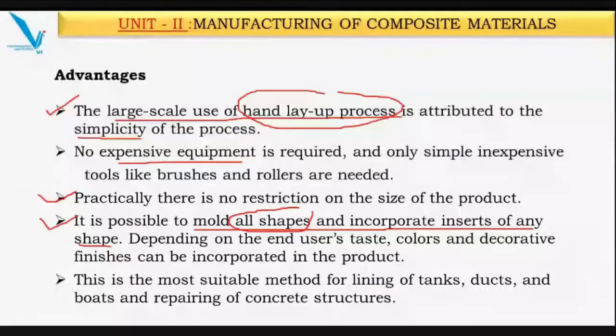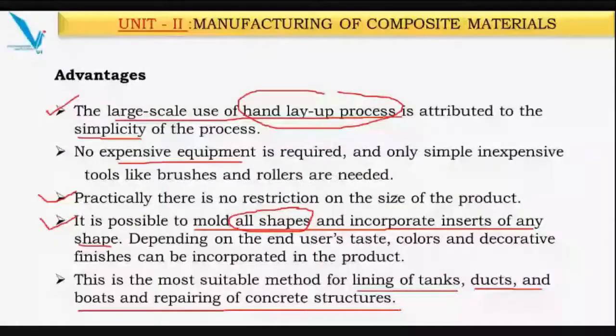Only thing is that you have to prepare that particular mold. Only that requirement. So this is the most suitable method for lining tanks. For repairing purposes, the hand layup method is generally used. If you want to fill up some holes or crack portions, that kind of repair can be done by using the hand layup process.